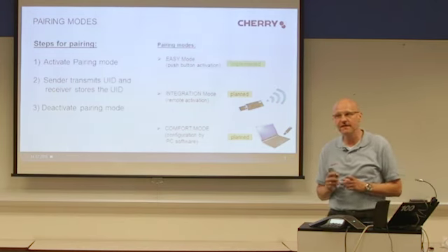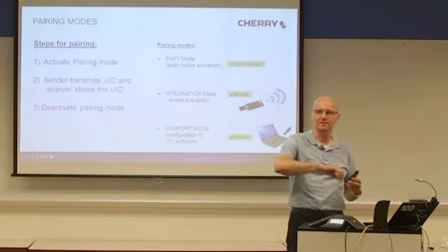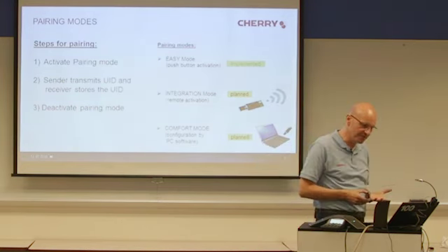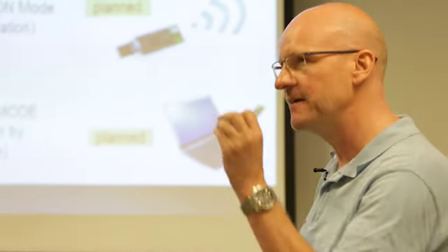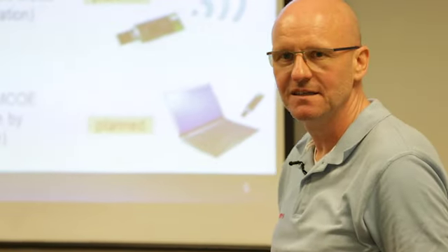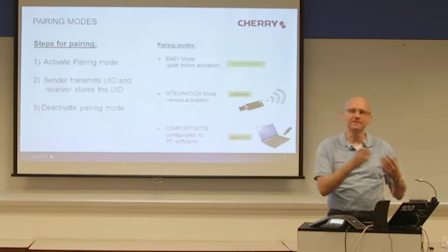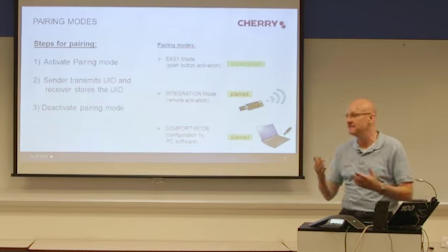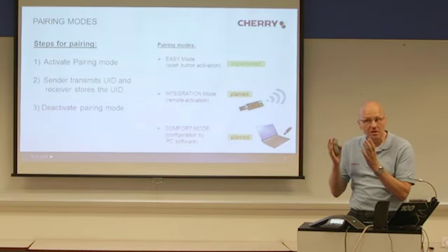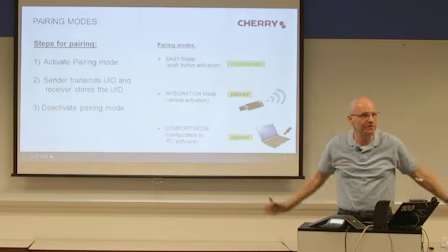It's necessary that we make a pairing procedure of every sender in the system to the receiver. This pairing procedure means that I say to the receiver, hey, I am the sender number 17, and when I send a switch signal to you, you have to react. And for this, we need a so-called pairing procedure. In this pairing procedure, the sender is learned to the receiver, because the receiver gets all information in the air from every sender which is around him.